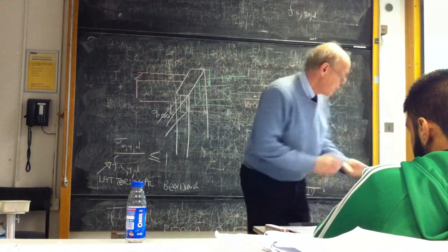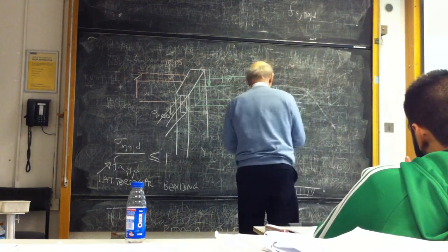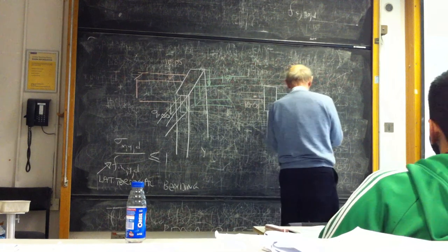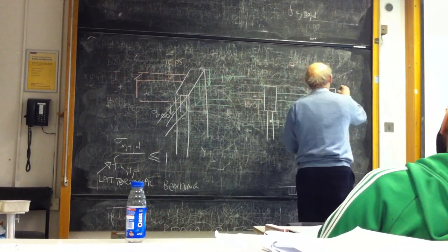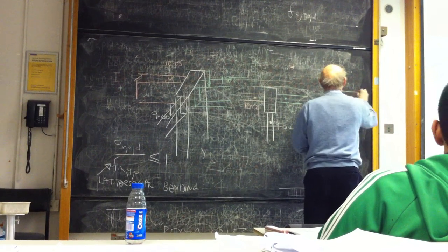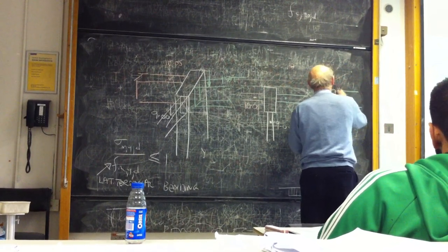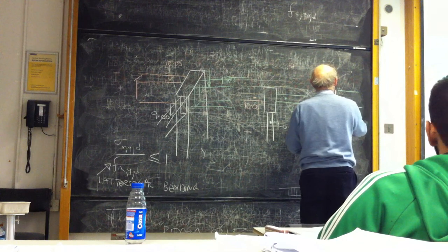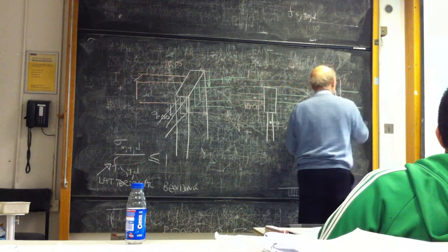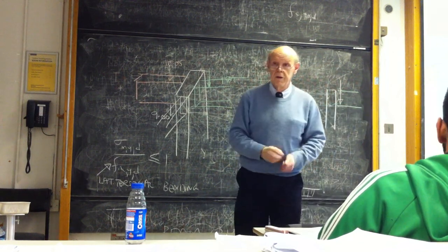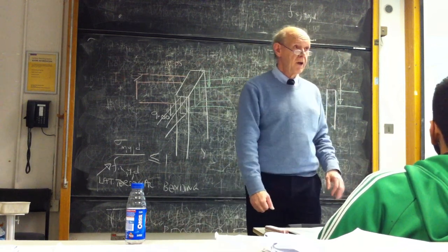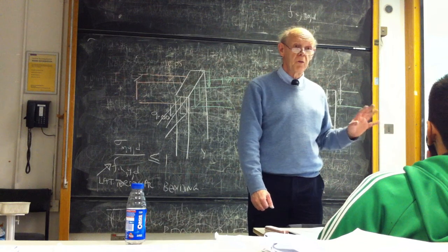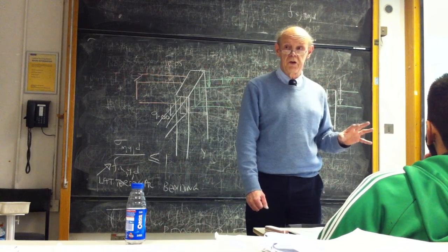using joist hangers, so that if I draw one of the details, if I draw that one, for example, what we're saying is you've got the column like that, and the beam is connected to it through some sort of hanger like that, so consequently the load is actually applied somewhere about there. And there's an example in the notes of what joist hangers look like, and if I put it in the exam paper, there will be a drawing of the joist hanger, so you'll be able to work it out for yourself.